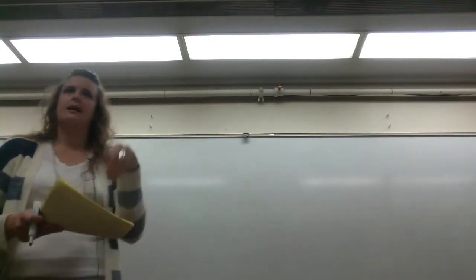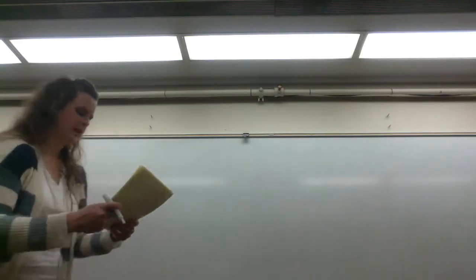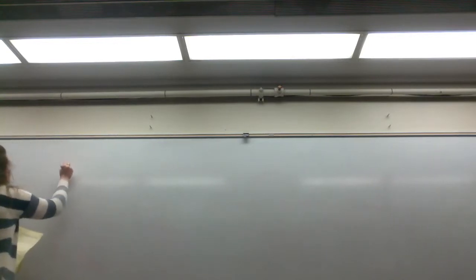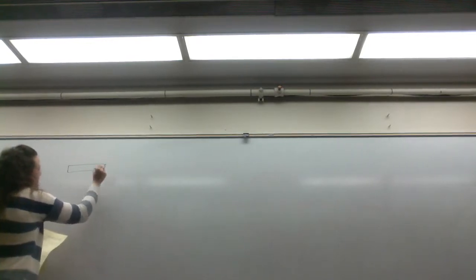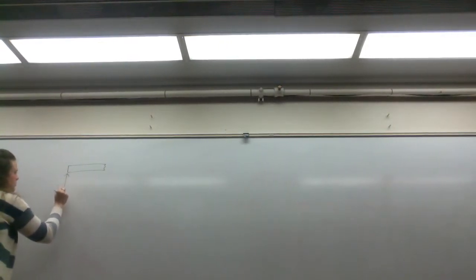So if you remember this example from last class, we have this beam with just a vertical force F loaded at 3/4 L. To solve for the internal force at C, we cut the beam. We had previously solved for our reaction forces at A: that A_Y force to be 1/4 F. There was no lateral force in A_X, even though it's a pin constraint. A_X ended up being equal to 0.